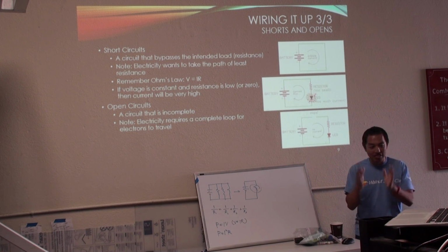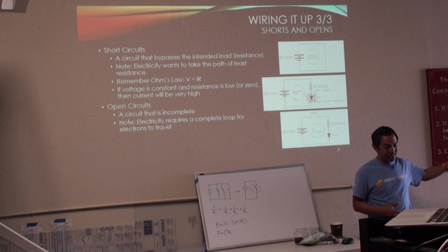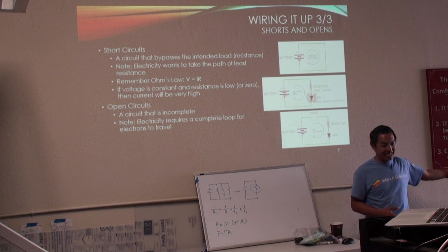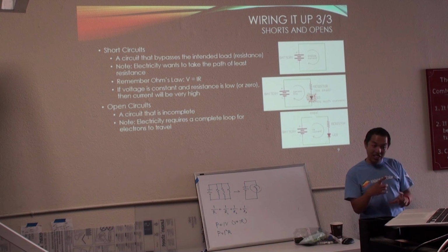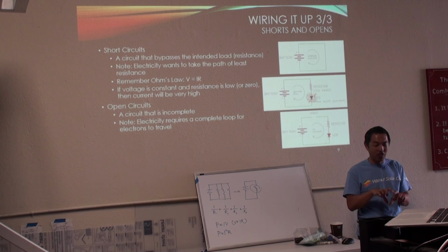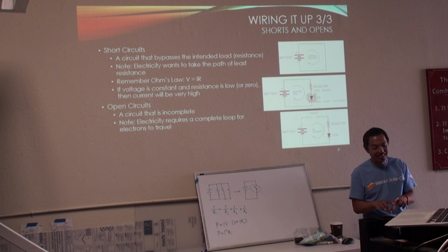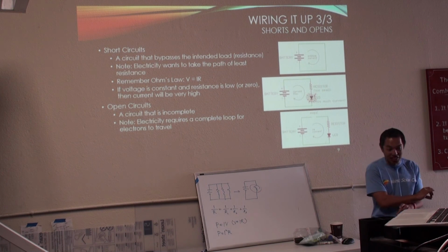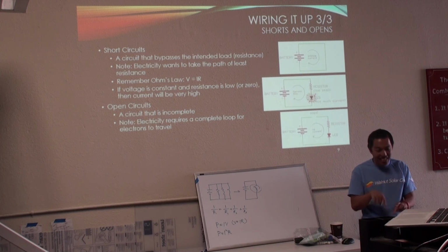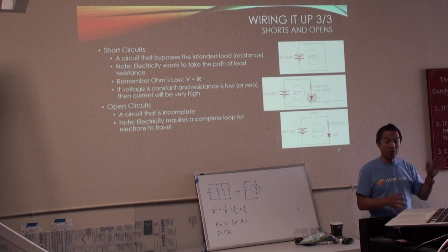I've got to drive the voltage to be 48 volts for our motor and motor controller. If I provide more than that, then because its internal resistance is a particular setting, it could provide too much current than the motor controller or motor can handle. If you do too little, then you're not providing enough current to the motor and motor controller to do anything. So that's sort of why we tend to operate things at a particular voltage level.